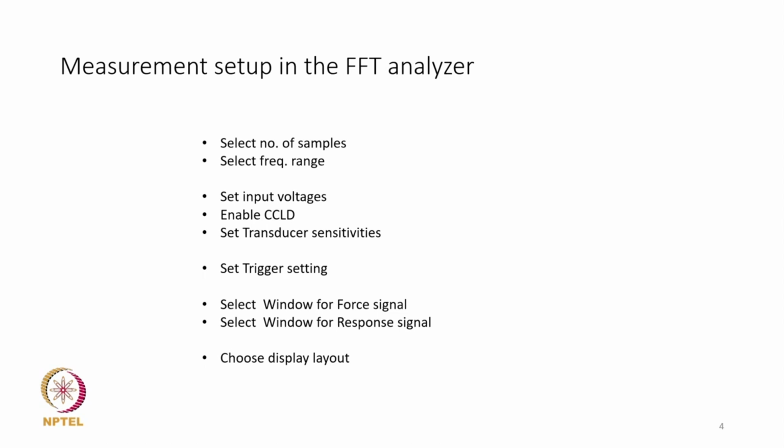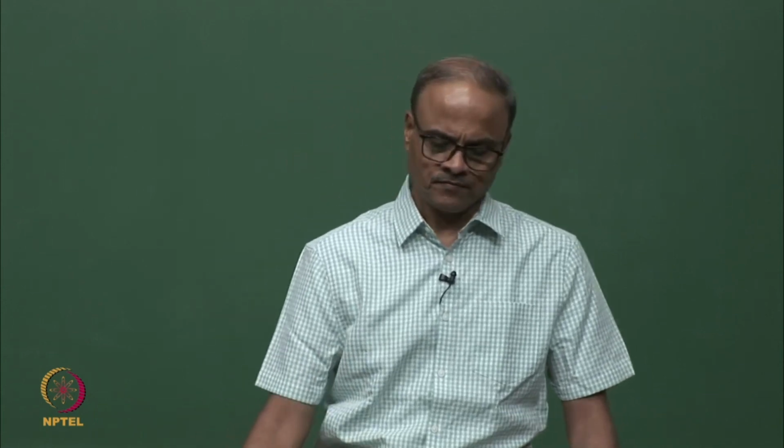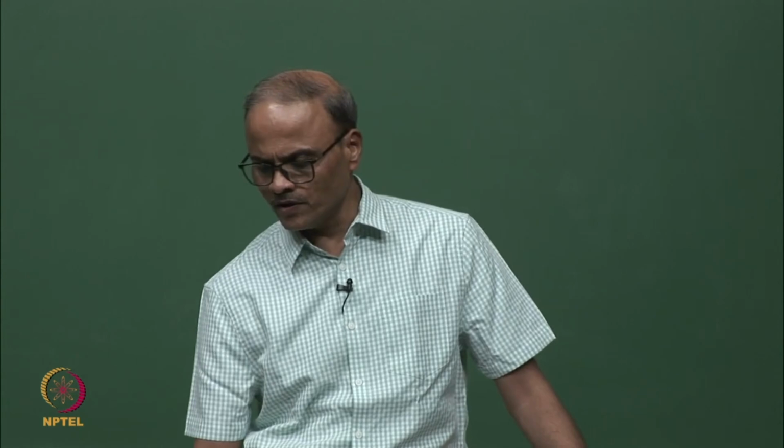And then the kind of display layout we want, for example we might like to have a look at the time signals, the power spectrums, or the frequency response and its phase. So whatever we want to see, according to that we need to choose the display layout on the analyzer. Let us go to the next slide.